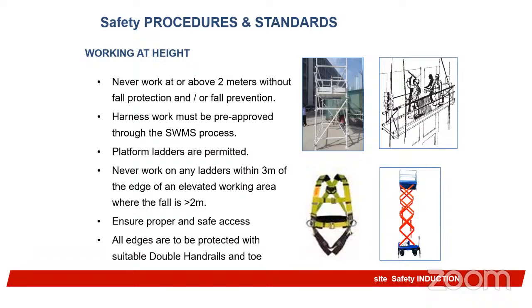Safe work method statement, because that's the full meaning of SWMS, so it must be according to what has been addressed in the method statement. Platform ladders are permitted also. We talk about whether they are permitted or not. Never work on any ladder within 3 meters of the edge of the elevated work area where the fall is greater than 2 meters. So when you are working and you want to use a ladder, this particular one can be reviewed based on what is obtainable on your construction site.